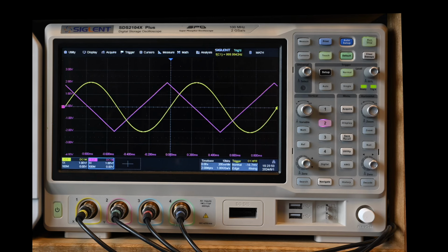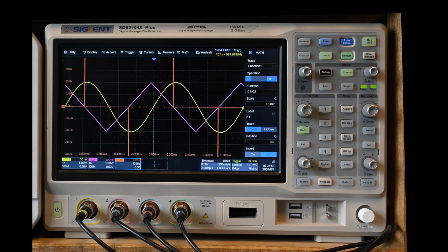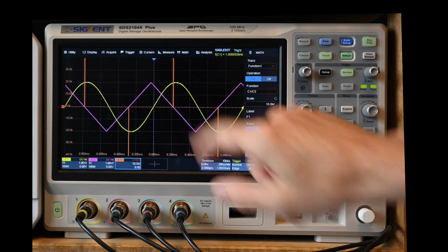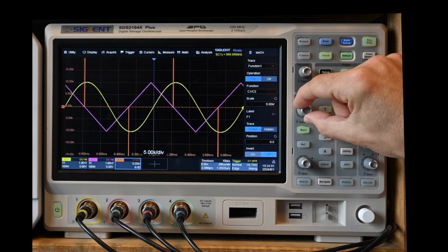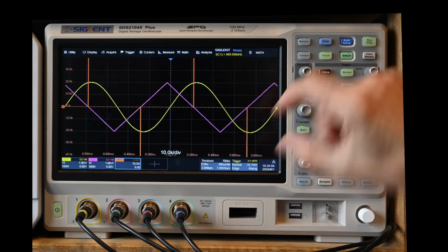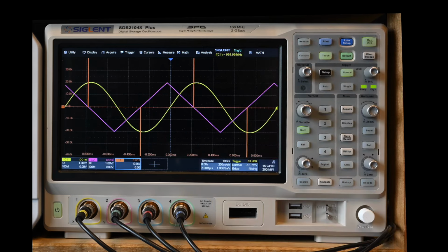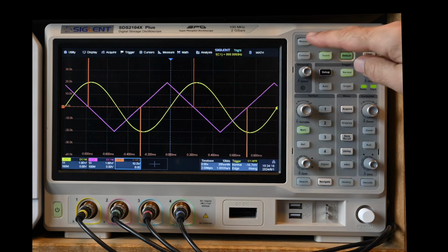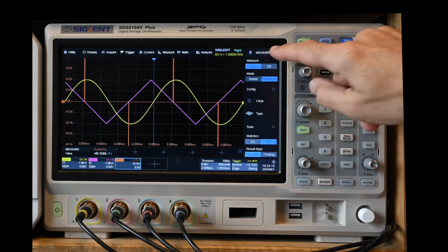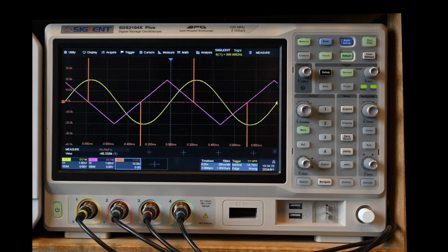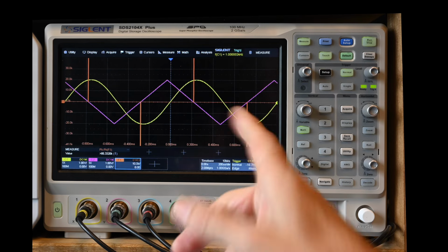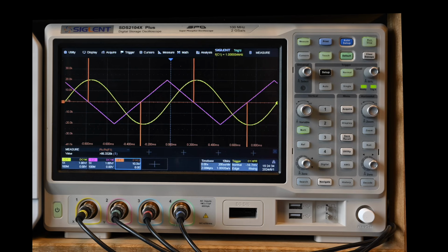So using the same waveform, I created the same math. And I get to see very high values. This is the smallest I can get, 10,000 per division. Again, a dimensionless value as it should be, but it still goes out of the picture here. I cannot get it any smaller. I also created a measurement that should show me the function, and it's clipping. We see it in this little symbol here, and it's clipping at higher than 85,000. So it doesn't deal well with divide by 0 at all.